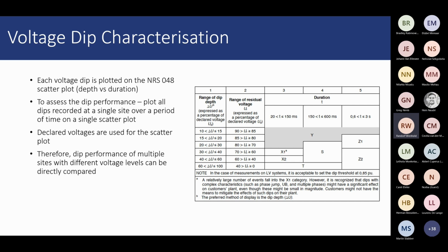Just on this note that Hein is touching on, the low power VTs are in a lot of cases cost and space effective. If you have switchgear in a place where you don't have a chamber to fit a VT, a low power VT can be fit on the termination of the cable. It is quite cost competitive with the cost of an actual VT. If you also consider the wider bandwidth of measurement, you will detect much higher harmonics than you could with a normal VT.